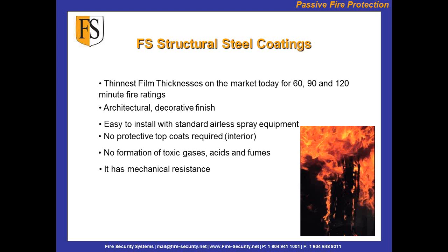So, for instance, the best determining factor, I think, is when you're looking at a water-based coating that carries 75% solids. So it's 75% solid, 25% water. Same with the solvent base. It's 75% solid, 25% solvents. Well, after cure, it's only 75% solids. There's no solvents left. It's all offed out into the air when curing.